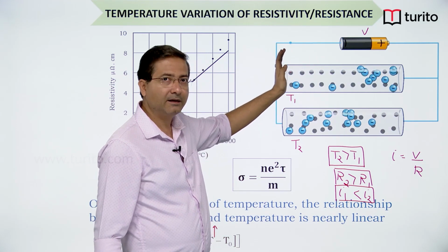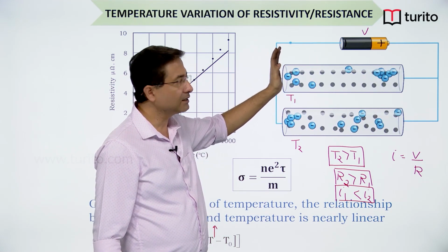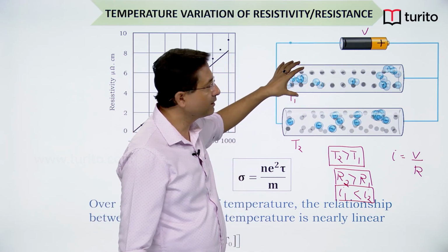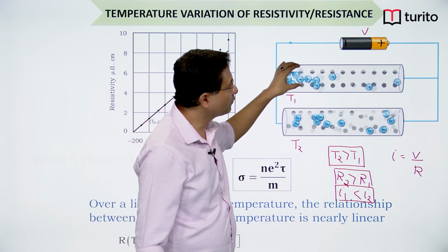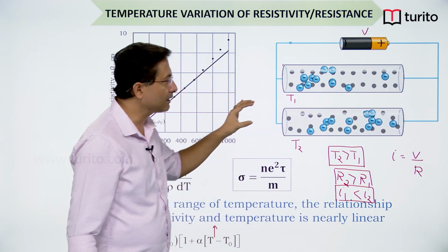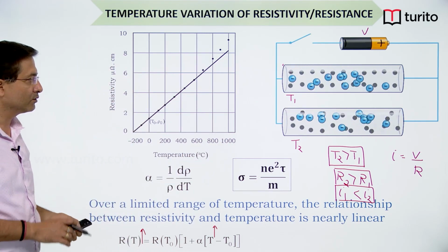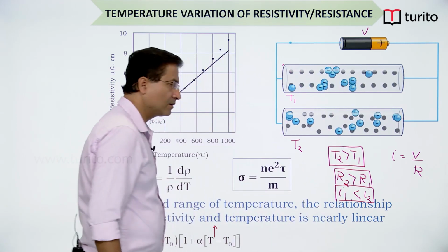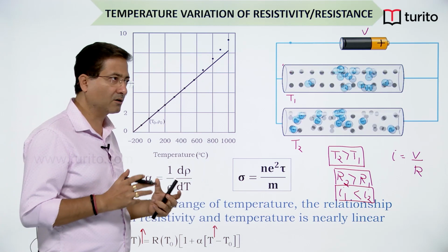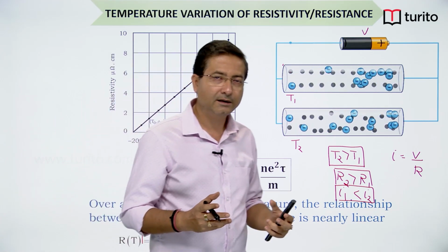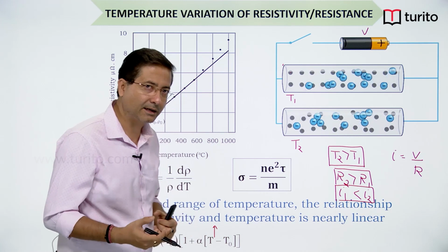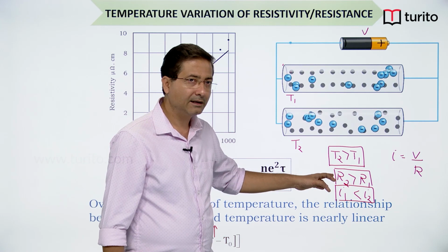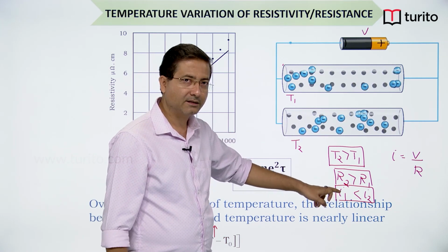But they are vibrating, they are fixed in the location, they are not moving from one part to another part, but these free electrons, as they are free to move, they can move from one part to another part, they start drifting. Okay. So, more the temperature, if I take same material, copper of same dimension, right, one is at lower temperature, another at higher temperature, one will be offering more resistance and current through that will be less.